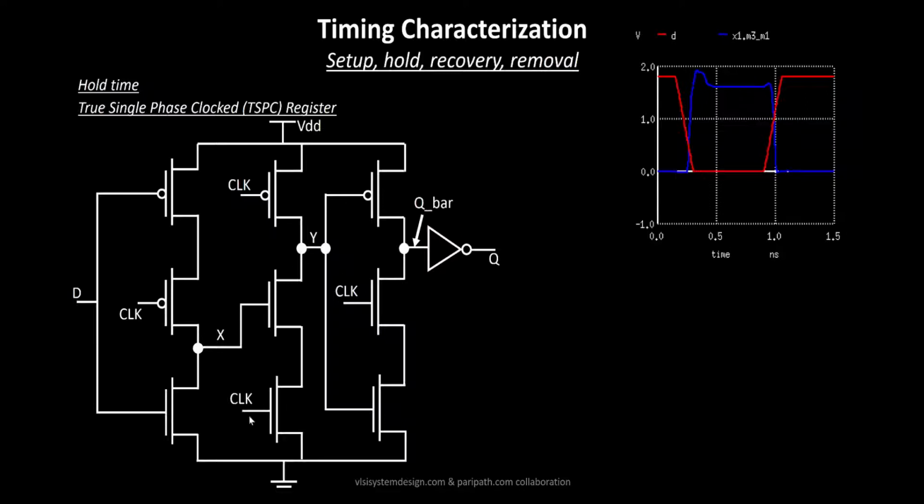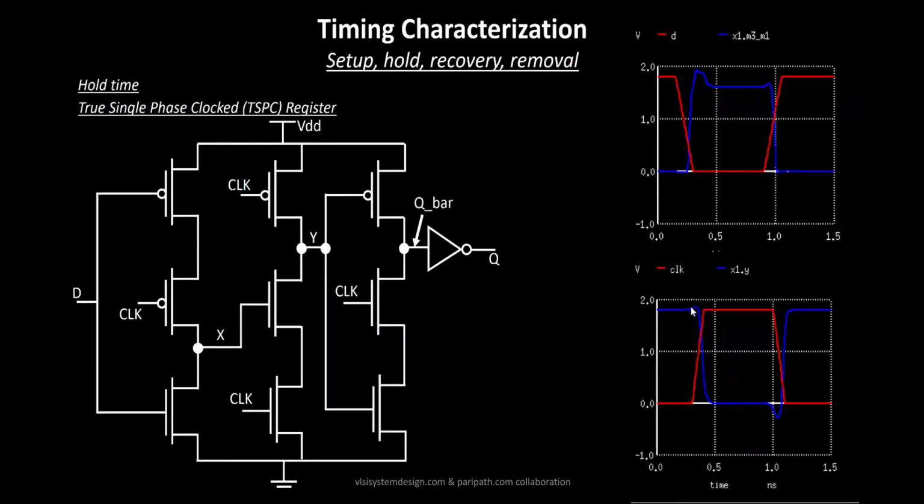Now again, whenever clock is 0, this particular MOSFET is basically turned off. So this is off, and this is basically logic 1 that you see over here. This is turned on, but it doesn't matter because it is not connected to the ground. So this is on, this is off, and your clock is 0. So PMOS turns on, and the node Y is being pre-charged to logic 1, because this connection is cut off. So your node Y is pre-charged to logic 1, and we have drawn it over here. This is the node which is pre-charged to logic 1, and Q underscore bar.